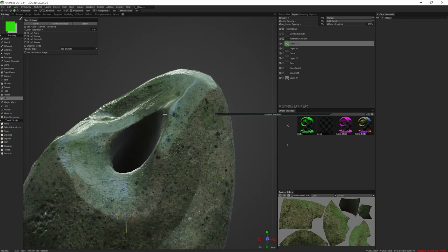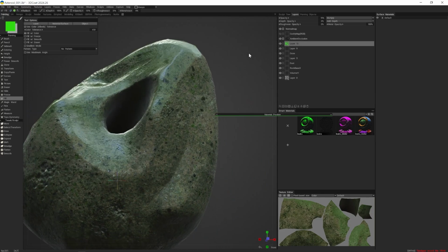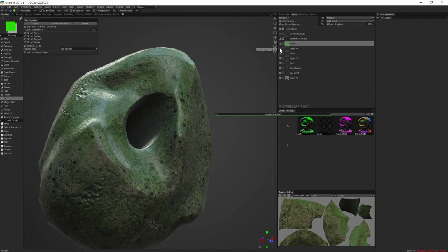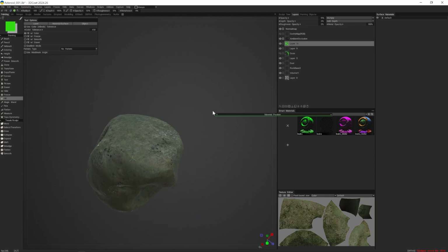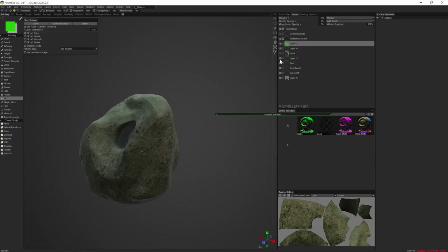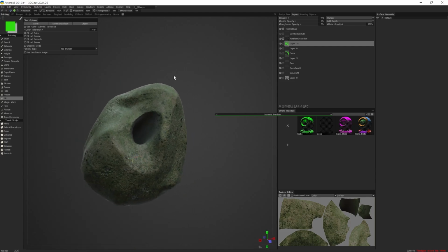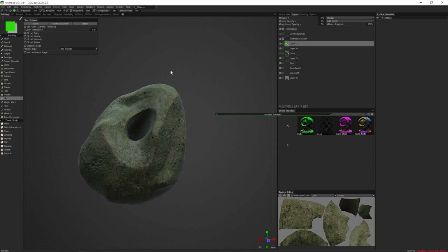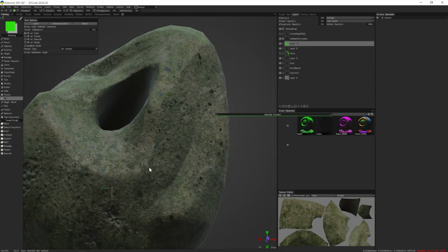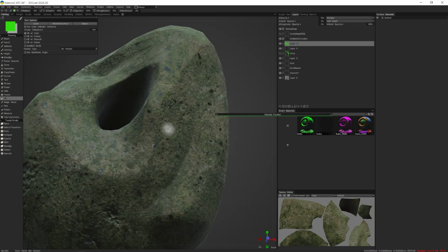the 3D low poly model. And the cool thing is all of the texture paint that I did on the Sculpt is still live and dynamic. It's linked to both. So I can still turn it on and off, right? It's baked, but I still have my layer structure intact, which is really, really amazing. So any Sculpt painting I did before, it's still present, and I can still work with it here on my lower poly retopoed mesh.